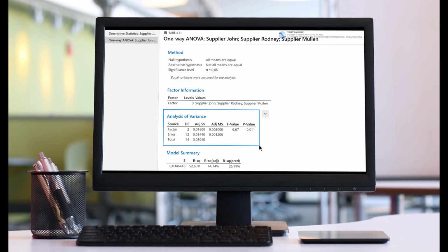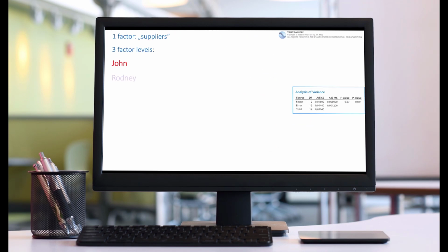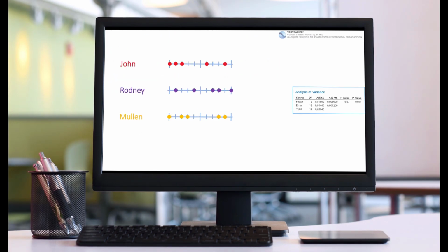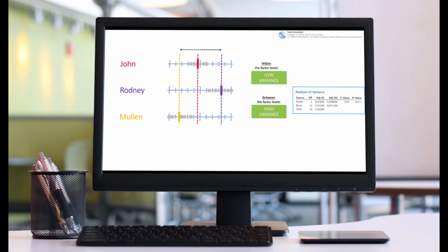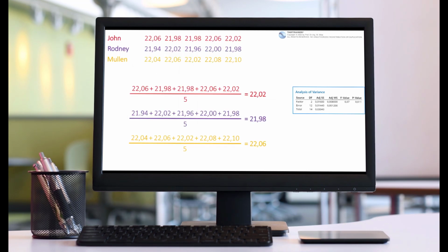Before we start with the actual analysis of variance, often abbreviated to the acronym ANOVA, we will first use descriptive statistics in this Minitab tutorial to get an overview of the location and dispersion parameters of our 3 supplier datasets. Before starting the actual analysis of variance, a discriminatory power analysis must be carried out to determine the appropriate sample size.